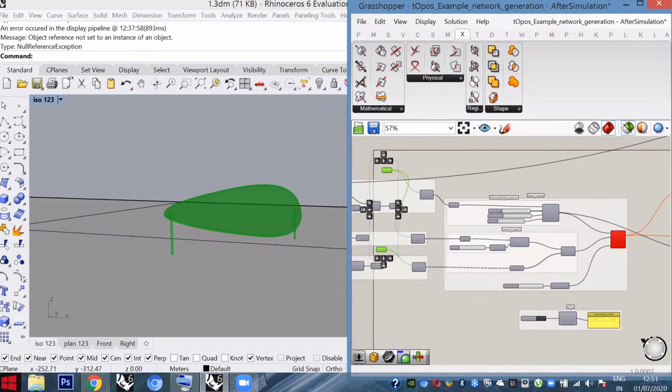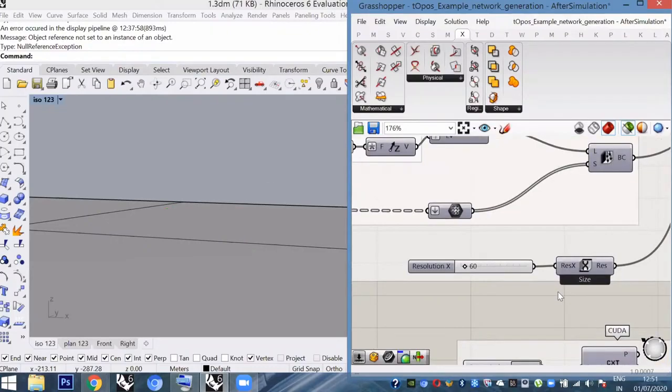I think I explained once that when you set the resolution, it's a resolution in the x direction. So the z direction will be divided with the same element size, but not with the same resolution. So if your plate is very thin, there may be no element at all in the z direction. Okay. So I will try that out too.